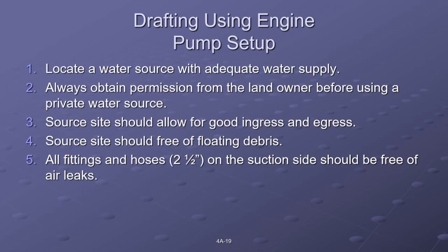Okay, so the general rundown is right out of the ENOP course of how to draft using your engine pump. And when they reference draft here, they're really talking about drafting and pumping back into my tank. And really, I draft every time I pump. I can draft out of my tank or I can draft out of my source. Either one of those is still pulling water and therefore drafting.